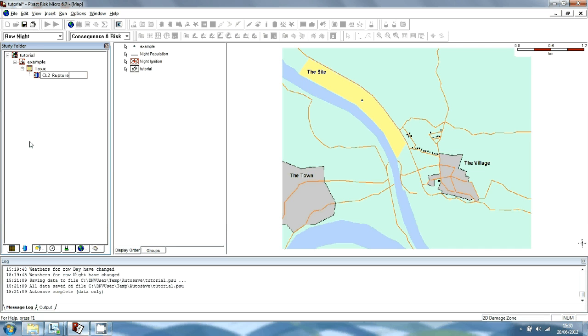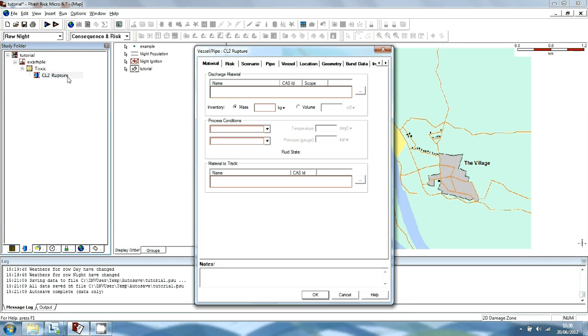To set up the input data, double click on the icon for the model to open the input dialog. All of the fields in the first tab section are blank, and those that are enabled have red borders. A field with a red border is a mandatory field which you must supply a value for, and you will not be able to run calculations for a model until that mandatory field has been set. This section describes each tab section in turn, including those that are not relevant to this particular hazardous event. Click on the Help button to open the online help if you want further information.